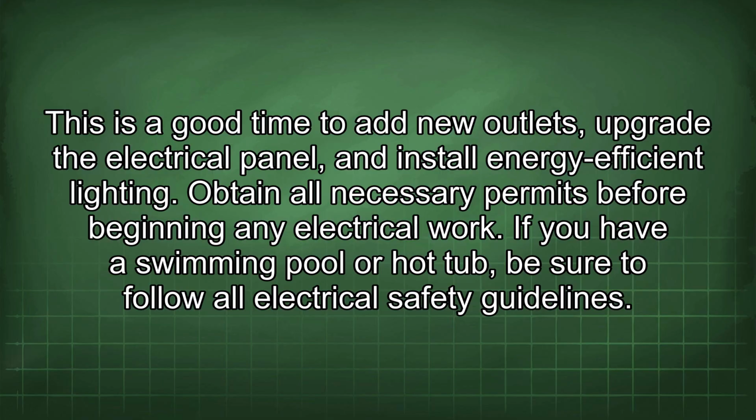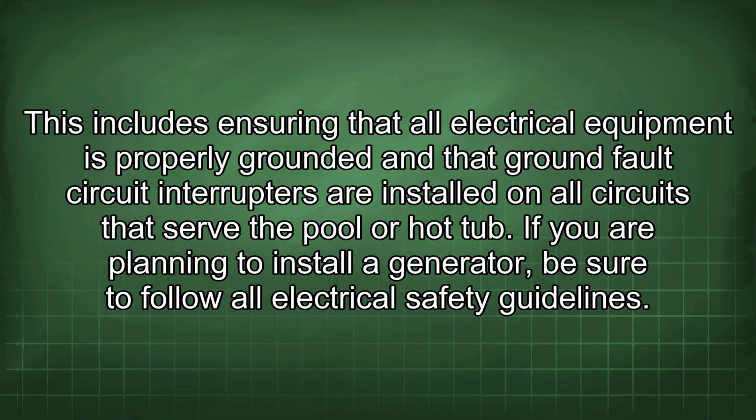If you have a swimming pool or hot tub, be sure to follow all electrical safety guidelines. This includes ensuring that all electrical equipment is properly grounded and that ground fault circuit interrupters are installed on all circuits that serve the pool or hot tub.